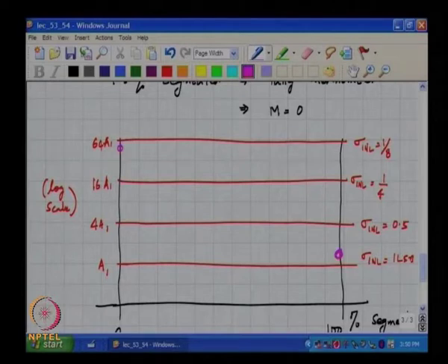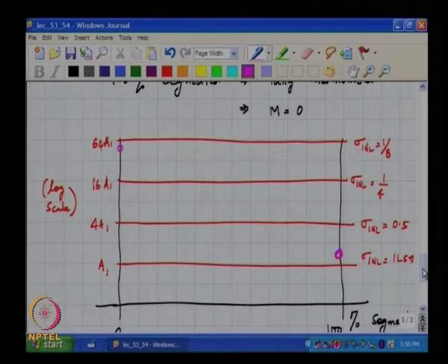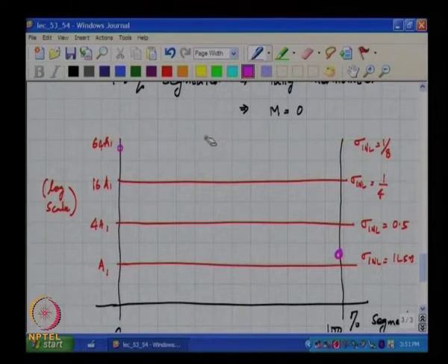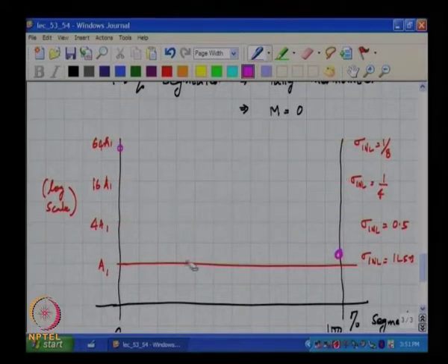It will increase, and it will increase exponentially because it is proportional to 2 to the m plus 1 minus 1, which is approximately 2 to the m plus 1, with m equal to n when you want a fully binary DAC. So, I am going to now erase all these lines.